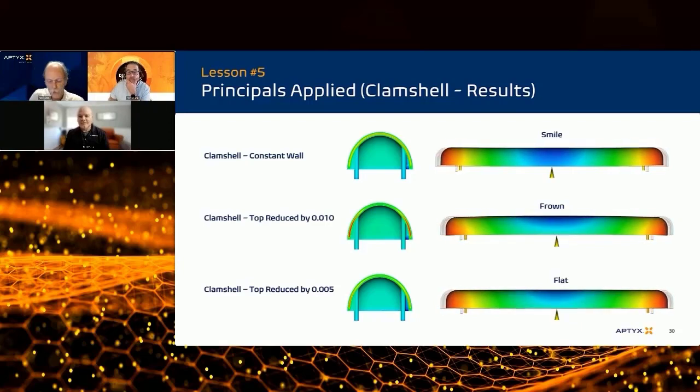Yeah. I had a recent project just that way where I was getting the part to go flat, like in this view, but when you did a cross-section, it was curving. And the reason it was curving at the time for these was I couldn't get the core geometry mirrored over 100% onto the cavity side. So I had to offset some of that, and some of that offsetting can create some warp across that middle. In those particular cases, we were able to overcome it. We used grooves, we used other techniques to try to help tame it down. Got it to a point that was acceptable, but it is an axis that you need to look at.